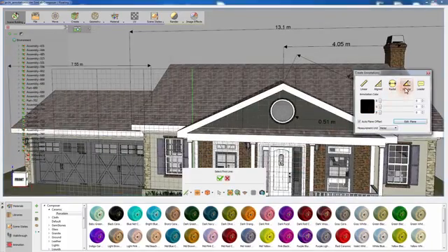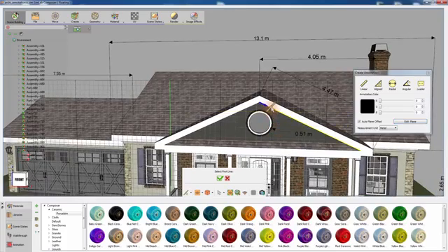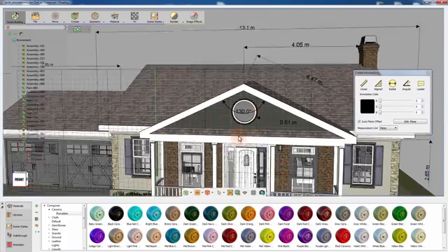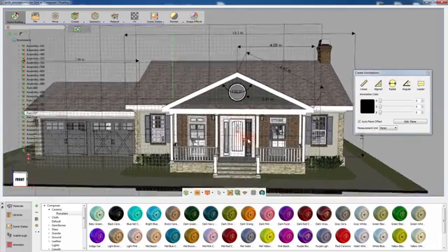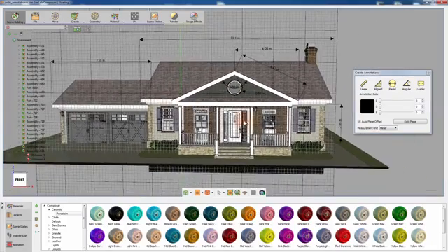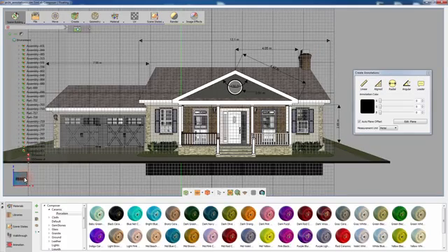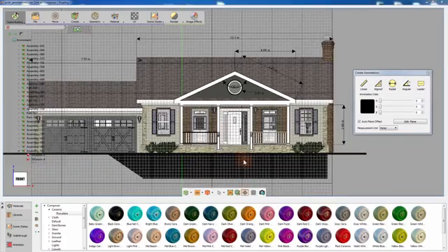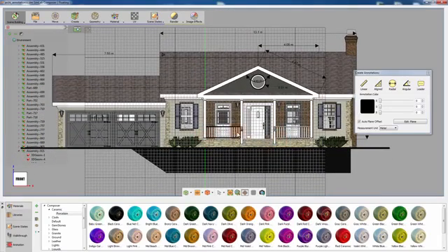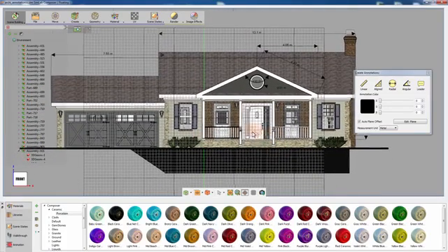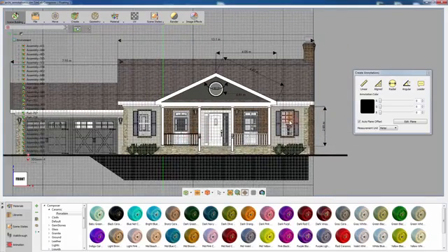Click on the Angular Dimension tool and click on an edge to set the first line. And then click on another intersecting line to measure the angle between them. Move the cursor to position the measurement's value and left-click to confirm its location. Aside from creating annotations in 3D space, you can set the camera to a front view and switch the camera from a perspective view to parallel view, which is the equivalent of an architectural front elevation drawing of a house. And from there you can proceed with adding annotations to your design.